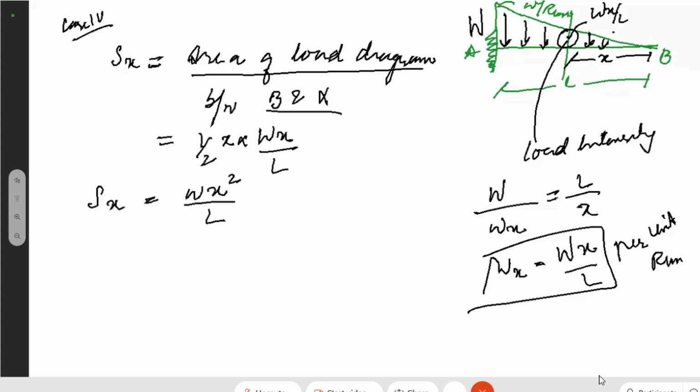Sure, sure. Look, whenever we have to calculate the shear force for beams which have uniformly varying load. Now this, I had made this triangle. What does this triangle mean actually? This means, for example, it has a load intensity which is varying this way, like 1, 2, 3, 4, 5, 6, 7, 8. It is varying linearly from point A to B. That is why I had made this a triangular load. Triangular means that the intensity of the load is actually varying from point B to A.